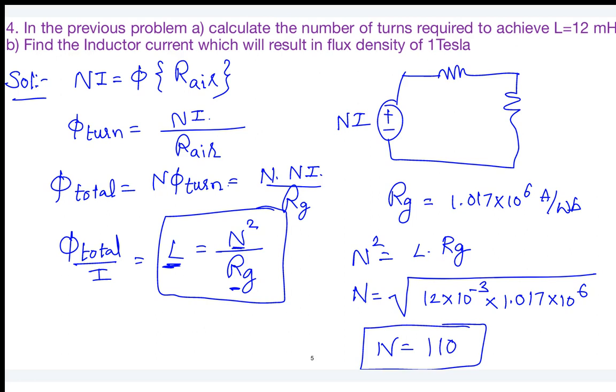If you don't know where to start, the simple suggestion in magnetic circuits is to draw the magnetic equivalent circuit, then apply the KVL. So automatically we'll come across the method of how to do that. If you're not aware of where to start, first draw the simple magnetic circuit, then apply the KVL. Then you will be able to know the procedure. So then do the second problem now.